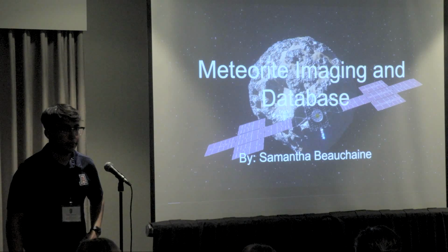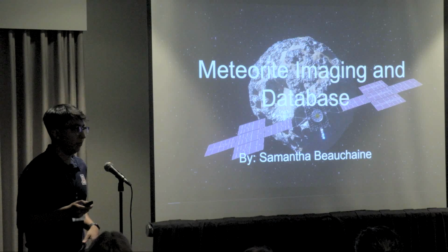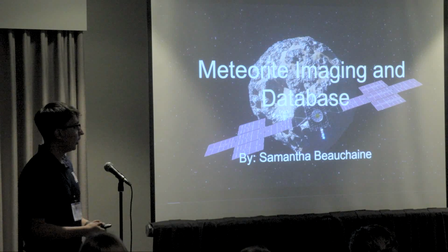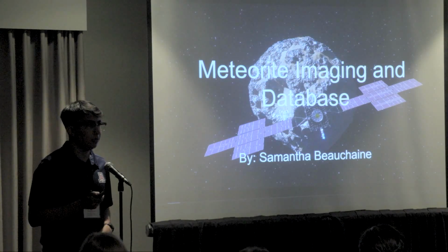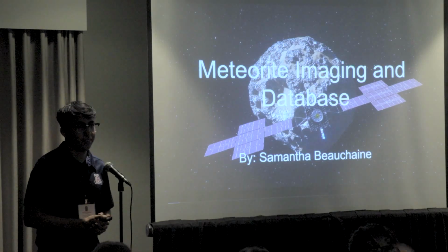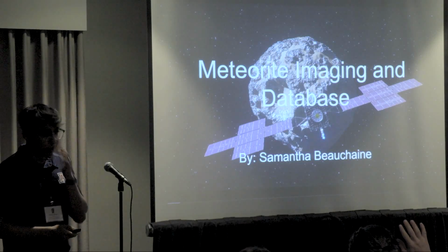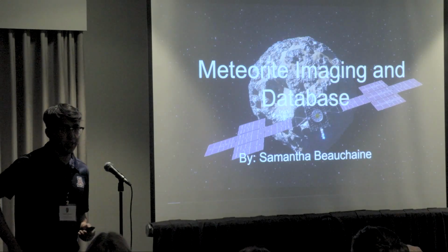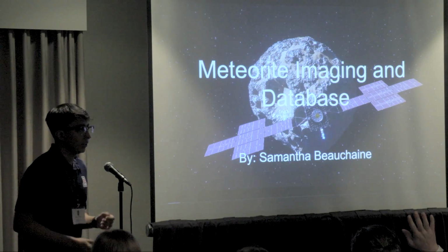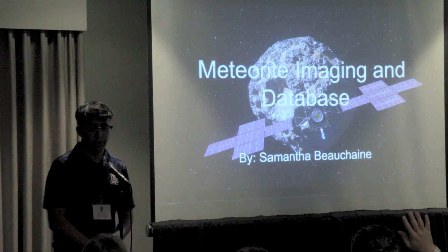Do you think once you put the casing in it will affect your sensor results? So we have tested with some encasings. As far as we've tested, there hasn't been any loss of integrity with the data. However, we have only been limited to what we could 3D print, which is just certain material. How frequently are you sampling? It all depends. It uses SPI. Right now, because what we're measuring isn't changing too rapidly, I'm sending about every tenth of a second.